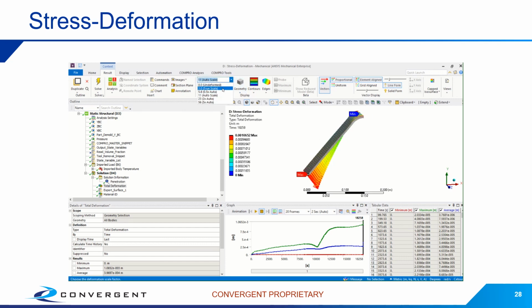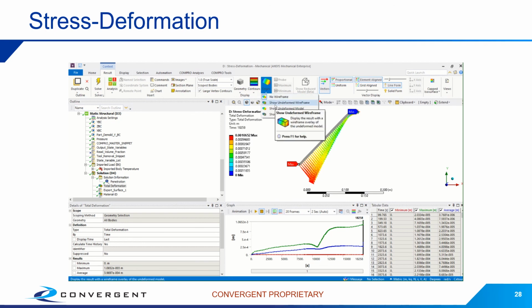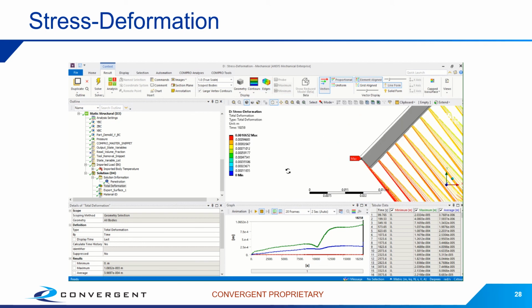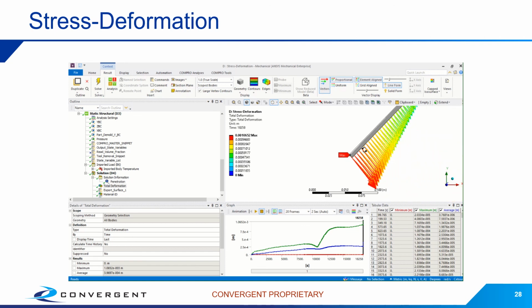Now, one thing that I like to do is plot this in true scale, look at it from the side view, and plot the undeformed model as well. So we can see again that there's spring in and there's a small amount. And again, it's up to you as the user to define what is an appropriate amount of tolerance or spring in. So using this data, there's various things we can do. Going all the way back to thermal design, your cure cycle, and ensuring that you're not gelling during a ramp, or minimizing your gel temperature too can also help reduce your PID.